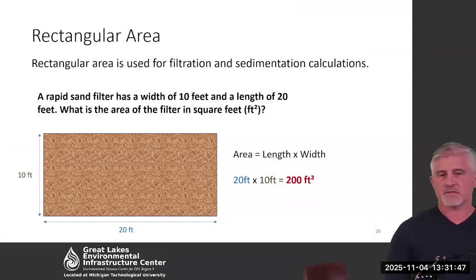We're going to look at two different formulas for area. In this case, we'll look at rectangular areas. That's important because a lot of our basins will be rectangular, and these are commonly used for filtration and sedimentation basins. So we need to know how to do calculations for those.